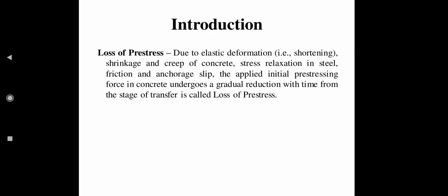So even at the time of transfer of prestress to the concrete member, there are chances of reducing the prestressing force from the recorded value as per the jack gauge. The various reductions of prestressing force are called losses in prestress.